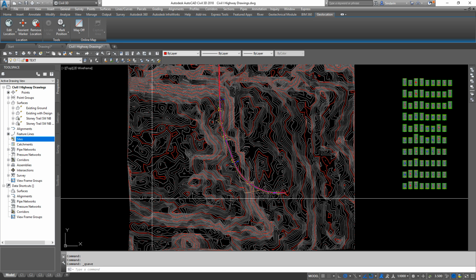Now, we don't have time to figure that out, and really on this kind of a surface that we have here, basically LiDAR, it's really difficult to figure out the contributing area. So the one that I've come up with is about 1.5 million square meters, which is a lot of area, but we're just going to design a pond to hold roughly 10,000 cubic meters of water.